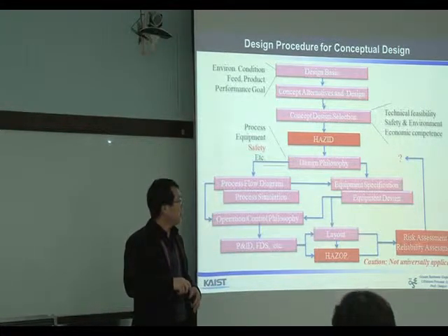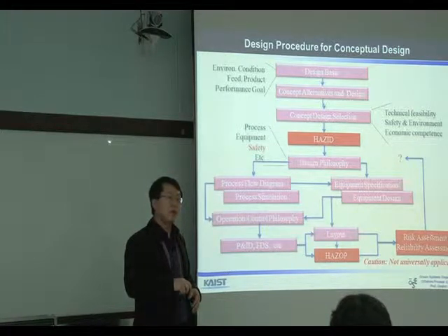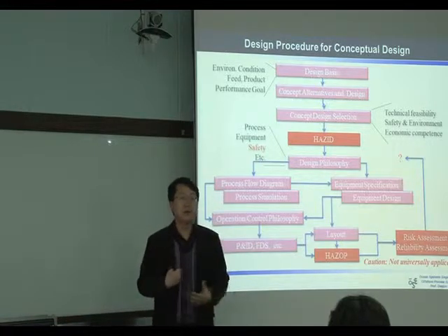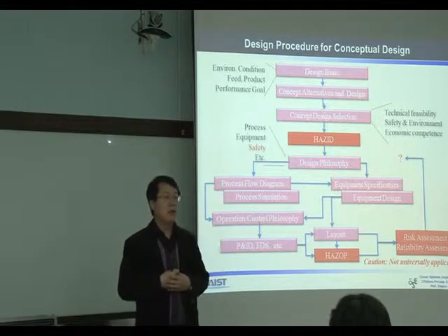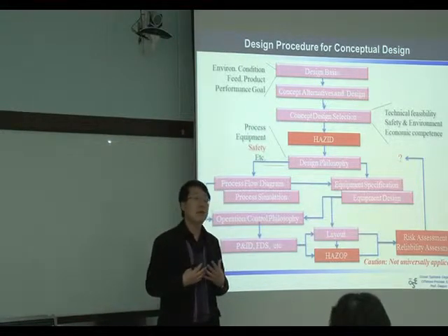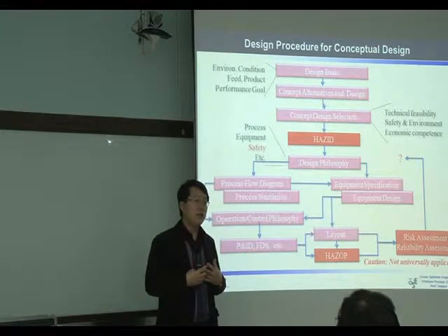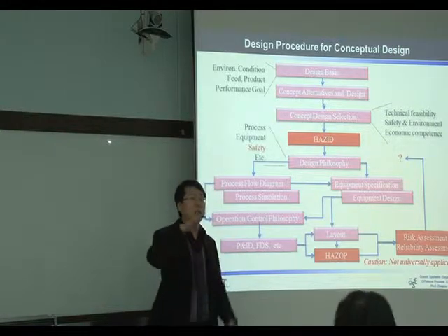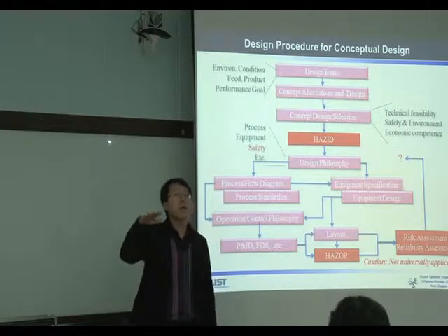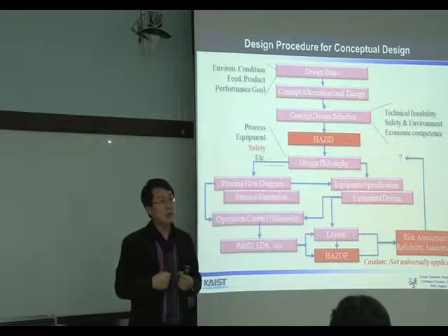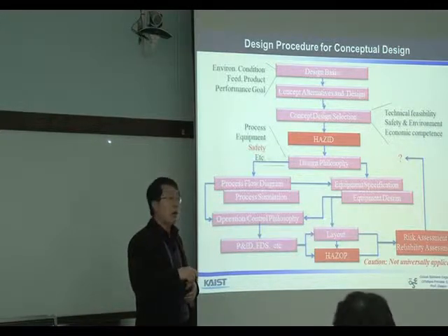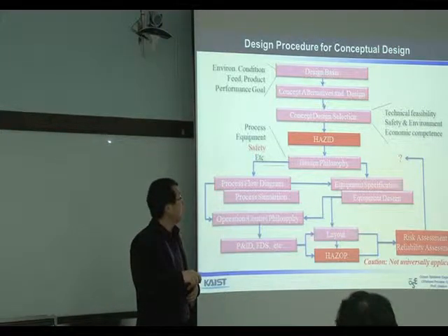Then we can carry out the risk assessment and the reliability assessment. If the result of the analysis is not satisfactory, for example, if the estimated system availability is less than the target value, we should change the system design. If the change is minor, we can go back to here.